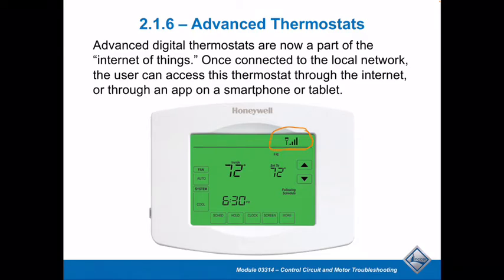The other thing that's really nice on a lot of these, like our phones today, is we've got touchscreen and a nice digital display. It's backlit. It's pretty good. One of the really nice features that these advanced and electronic thermostats have done for us is it's almost eliminated the need for anti-short cycle timers.